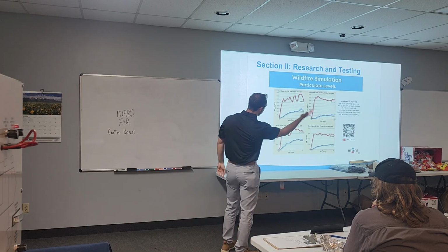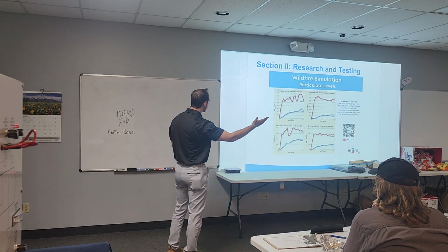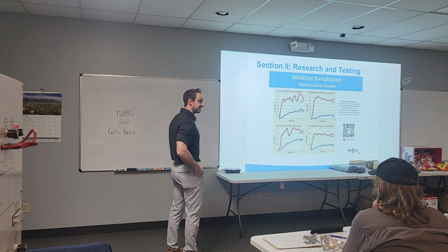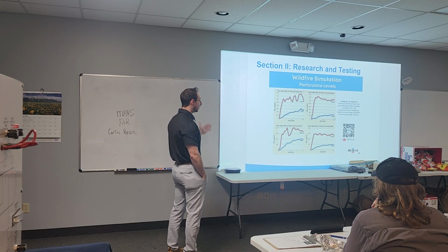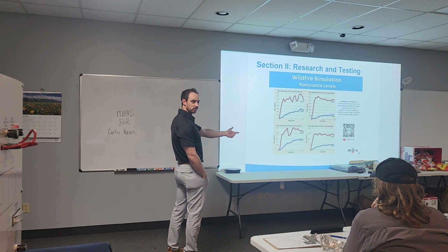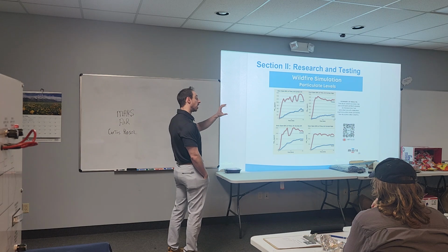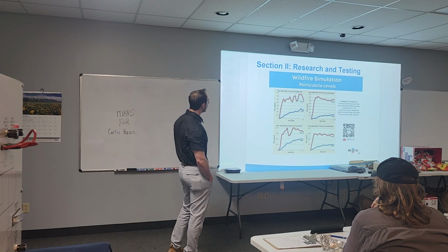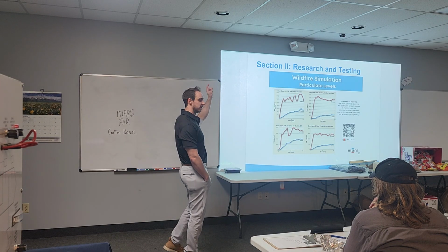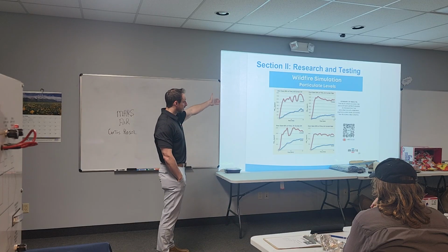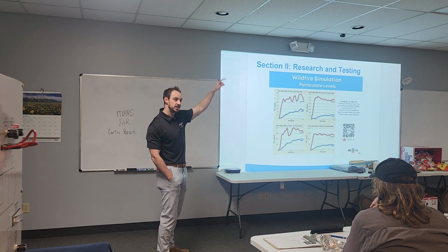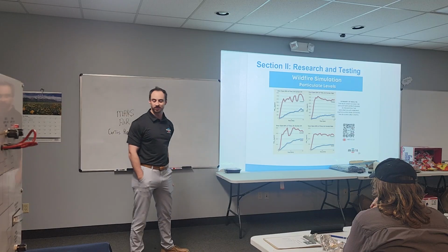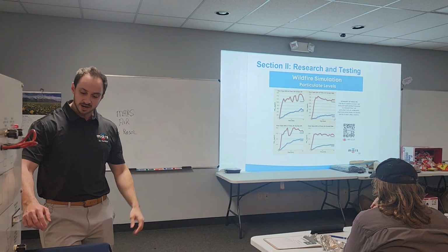So obviously the ones on the right, I don't want to block your camera, the ones on the right are a little less steep, and the ones on the left are a bit more steep. That's basically saying less particulates were getting infiltrated. The monitor we were using tracked fewer particulates getting into the building with the air curtains on. These big spikes in the red on the left show the varying amounts of wildfire smoke particulate on the outside. When the doors open, that's where you see the dips, because all of that is getting into the building. So, promising results there.